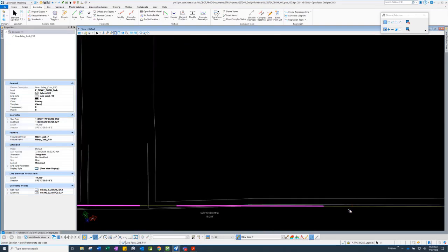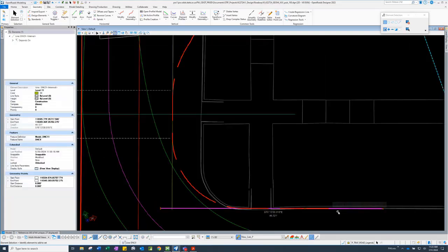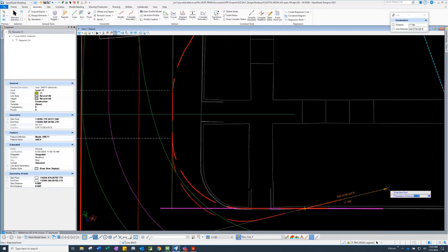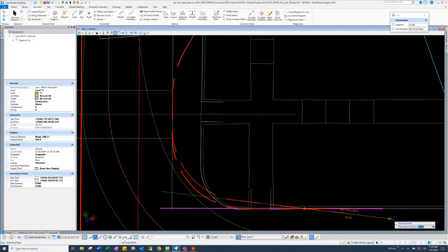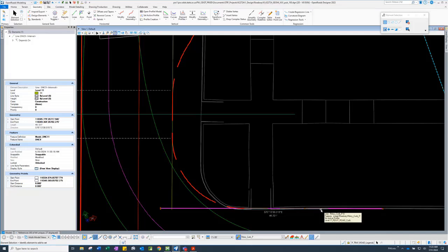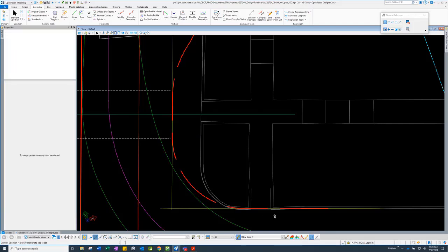And then the second one is the near snap on the construction line. And the reason for that is now if I need to move that construction line, the tangent will move with it. And you can see that there. So it holds the intent of my design to follow this curve line. And I can still move it along here. You could make it independent, but for me, I didn't have to worry about that tangent. Sometimes they get disconnected and I had to go back and reset them, and this way kept it in line with the curve because it uses the same tangent as the curve. So that's how I work.